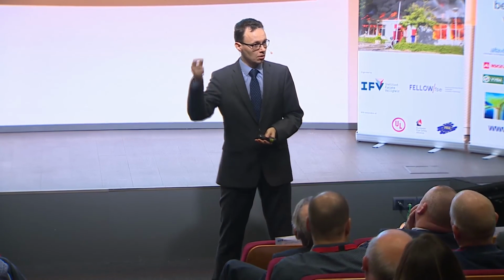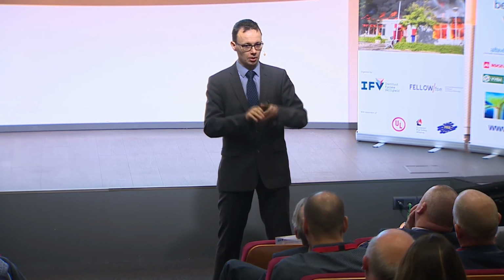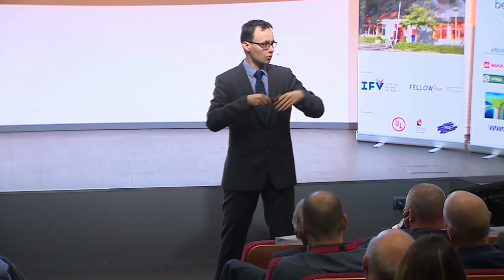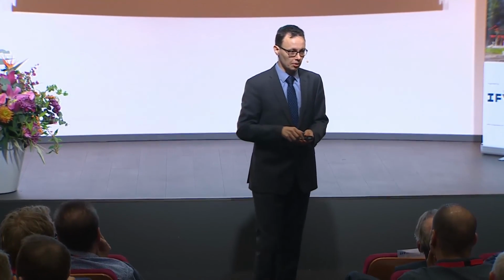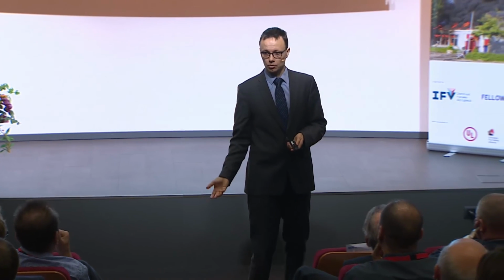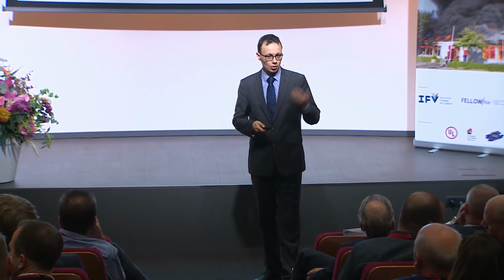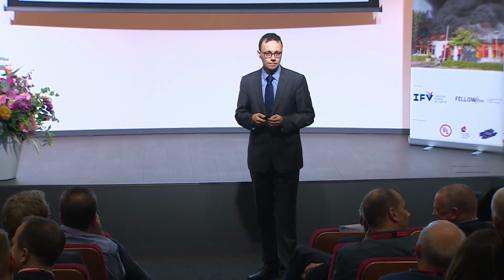At the activation, boom, it was pulled inwards and the pressure dropped. There was a short under-pressure peak, but then it basically stabilized. So the sprinkler caused an immediate drop in temperature and a negative term for the pressure equation in the modeling sense, and pressure was not a problem anymore.